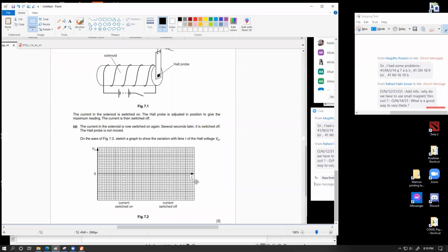So whenever the switch is just closed, current is going to start flowing through the solenoid, and the current will increase for a small duration. And just after a little while, the current will reach its peak value. For the duration when the current is increasing, the magnetic flux produced by this solenoid will also increase. And after the current has become constant, then the coil will simply keep on producing a constant value of current or constant value of magnetic flux.